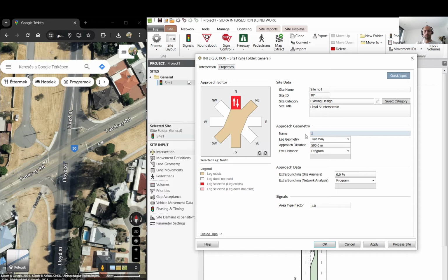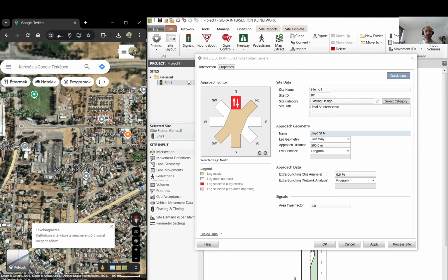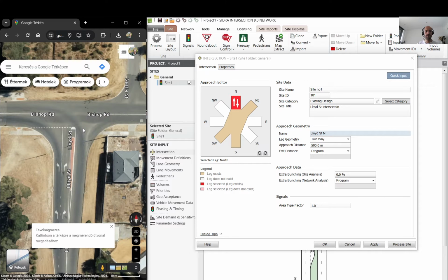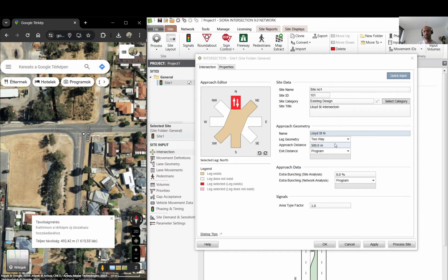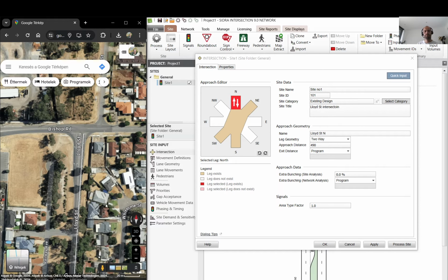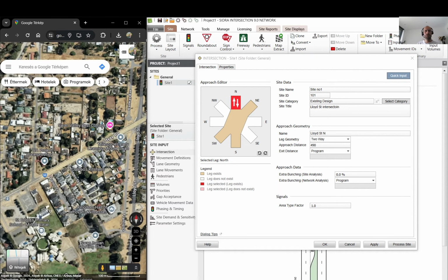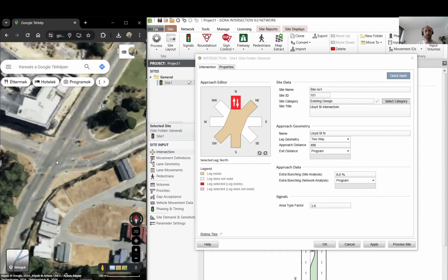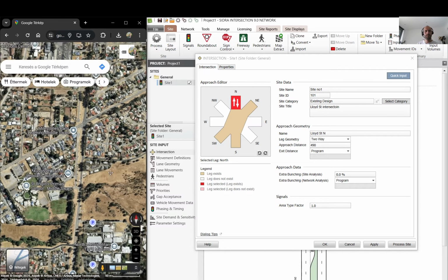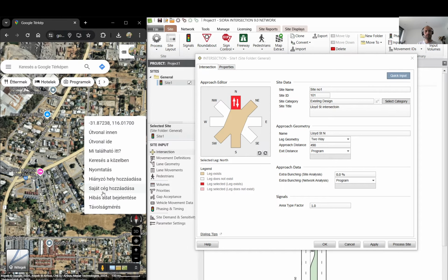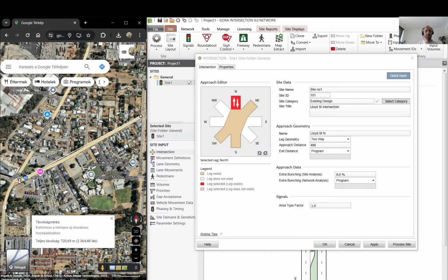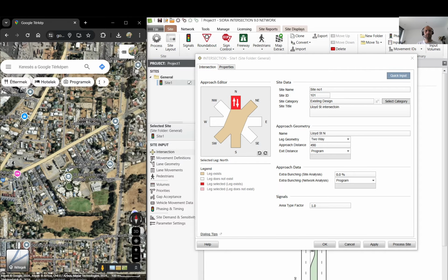So here you put Lloyd Street North. Two-way approach distance. What you measure is the intersection upstream there. So it's around 490. Then if I just check there are no intersections nearby, so this is way more than 500 meters, I think, or maybe not. Let me just have a look. If it's more than 500 meters, it's like 720. You probably don't need to worry a lot about it.